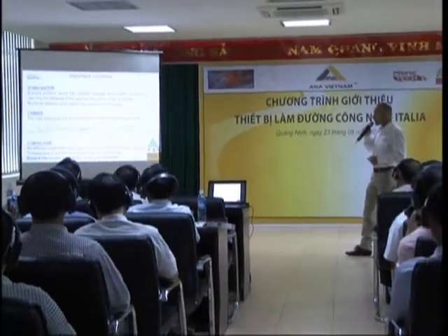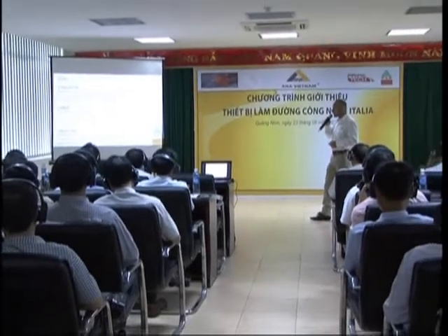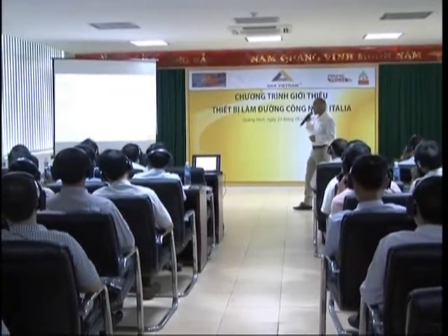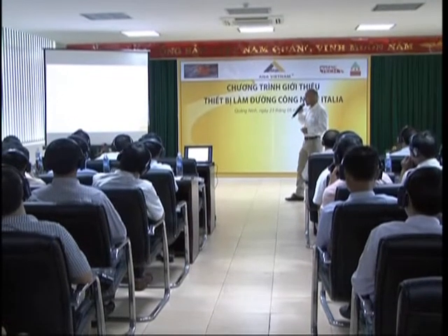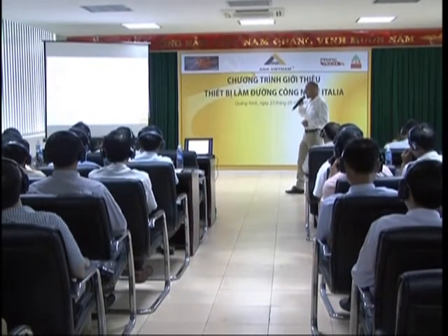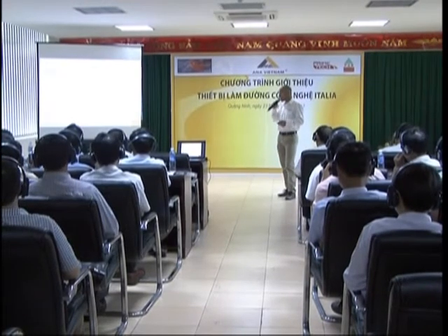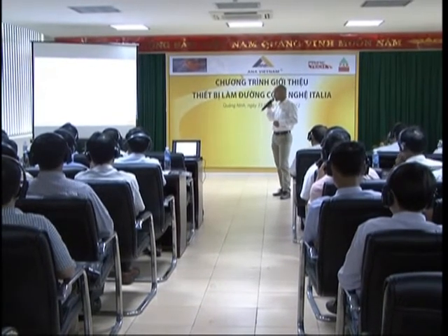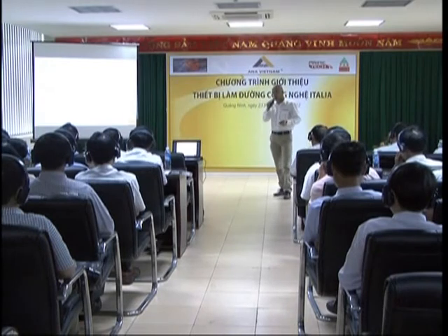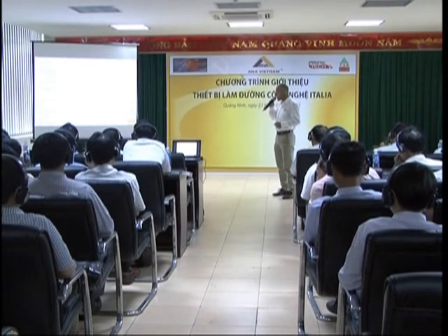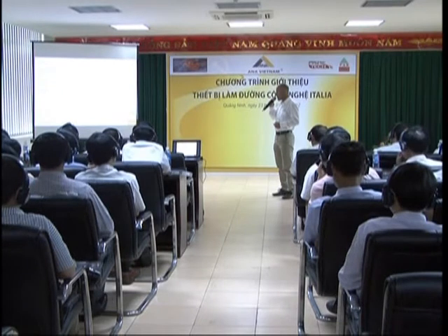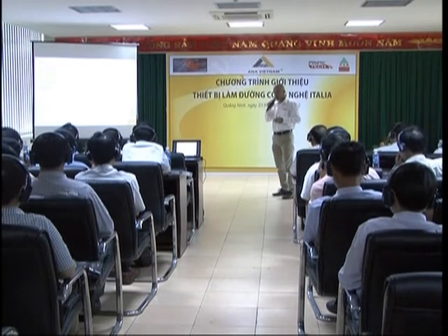And then the third concept we need to understand is compaction. Once you have made the road stable, which means everything the same size, once we have made the camber, we have to compact. So, of course, we compact by trying to reach as much as possible 100% compaction, if we can. And this is important so that the heavy dump trucks don't damage the road too much.